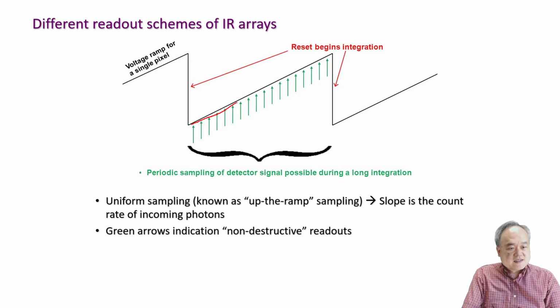If a cosmic ray hits, what you see is a gentle slope on that pixel, then a certain jump, and then the same slope as before the cosmic ray hit, because you are receiving a constant count rate from your source. This type of sudden jump or change due to a changing electronic environment can all be managed and recovered through software in the subsequent data analysis.